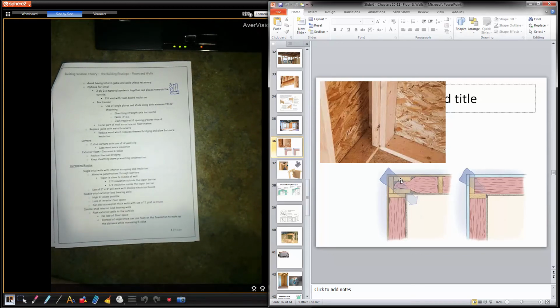Never had a problem. Most sidings require strapping, so just go for wider strapping. But putting that blocking there for exterior finishes really cuts down your insulation. So we typically do the L corner without that piece. But that being said, it still compresses the insulation.